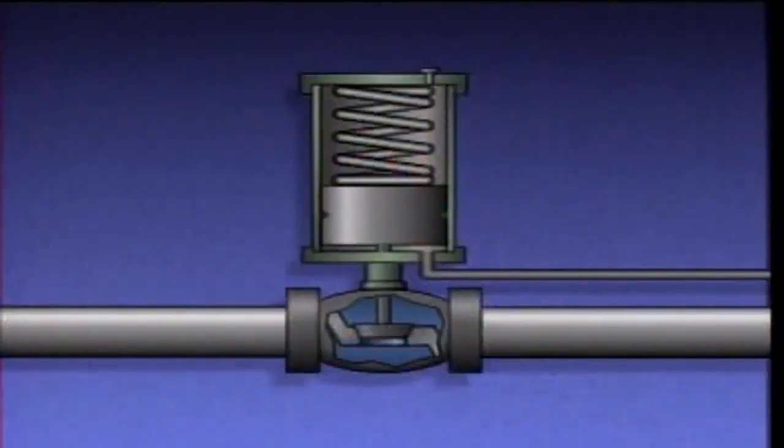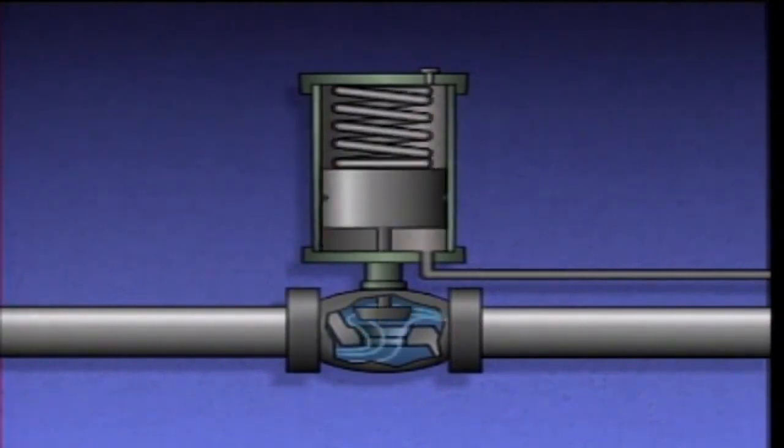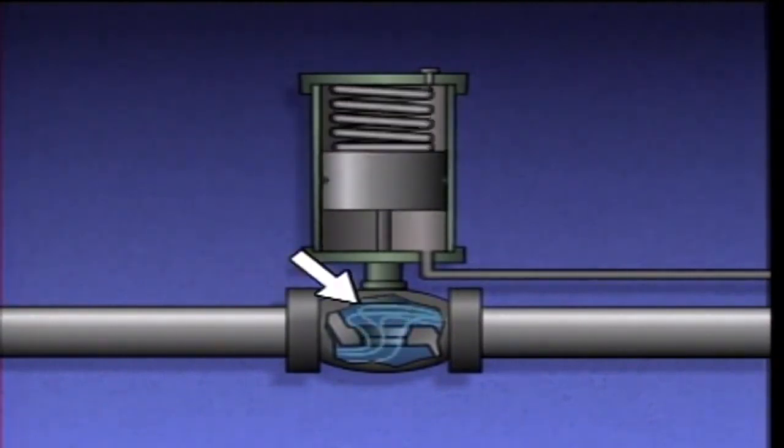This is one type of piston actuator. It's called a single-acting piston actuator because a controller or similar device controls the air pressure on one side of a piston. When air is fed through this air supply port, the piston moves along in a cylinder, compressing a spring and opening the valve. Air on the other side of the piston leaves the cylinder through an air vent.